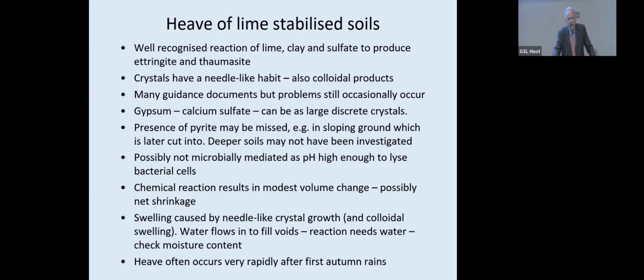The chemical reaction, lime plus sulfate plus clay, may actually end up with a net slight shrinkage overall. The thing that causes the swelling is the way the needles grow, jacking the system apart, or the colloidal material swells. And it seems that either water is essential for that reaction or flows in to fill the void created by the needle-like crystals. They're a little like props pushing the soil apart. Most chemical reactions that we see produce a slight shrinkage, like the setting of cement. But this one produces expansion by pushing mechanically the soil apart, and water fills the voids.